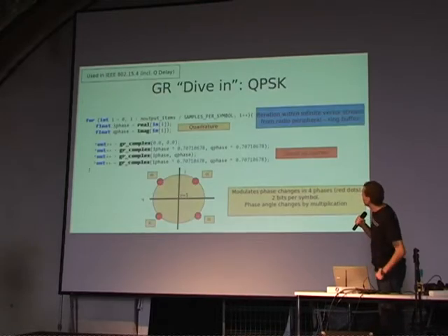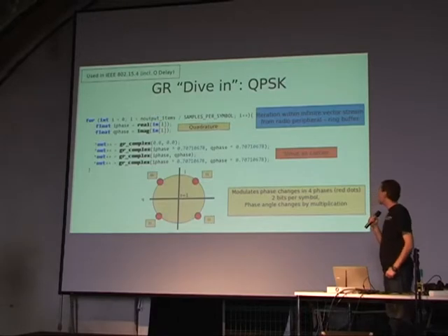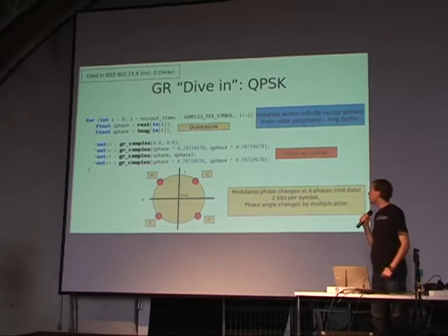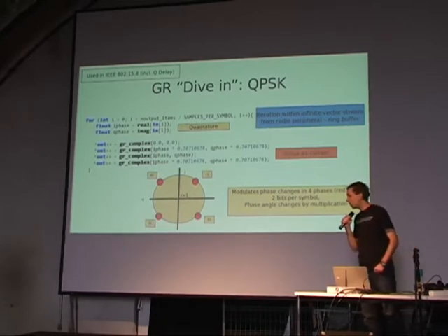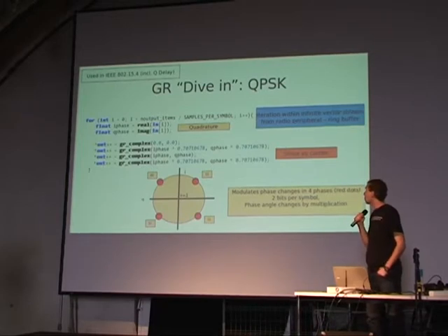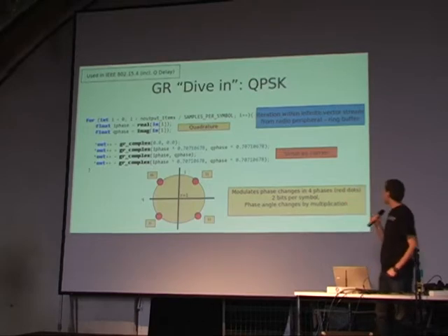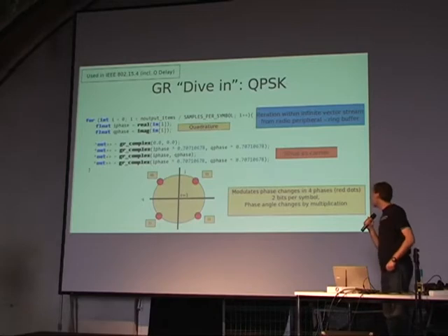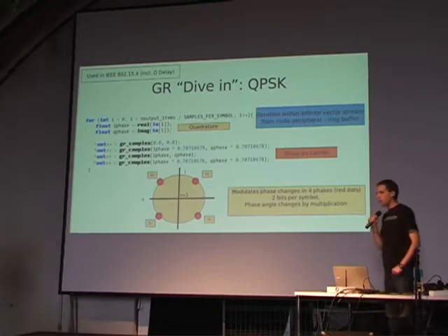So we can look at code, which here is code for QPSK, which is quadrature phase shift keying. That is used in IEEE 802.15.4, but there is no Q delay shown here. What this code is actually doing is, at first, an iteration within the infinite vector stream. That is because there's a ring buffer that is used to handle the vectors from the peripheral, so that we have access to that kind of value set.